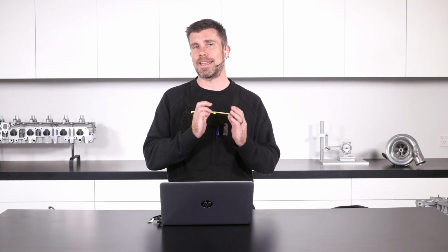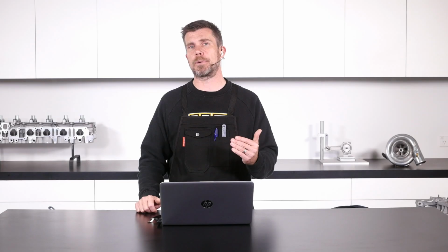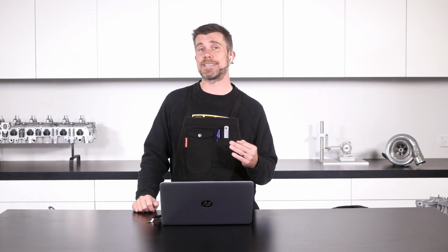Well, the reality is, unfortunately, yes, it will, because that is, again, that narrow view where we're only looking at the inlet side of the engine. So the exhaust side is just as important. What's going to happen there, despite the fact that the barometric pressure is actually dropping, and we're accounting for that in our exhaust pressure, because we're trying to maintain that same manifold pressure, as the altitude increases we've got to increase our wastegate duty cycle to drive the wastegate closed more and more in order to maintain that boost pressure. And what this does is it creates an increase in exhaust back pressure pre-turbocharger.